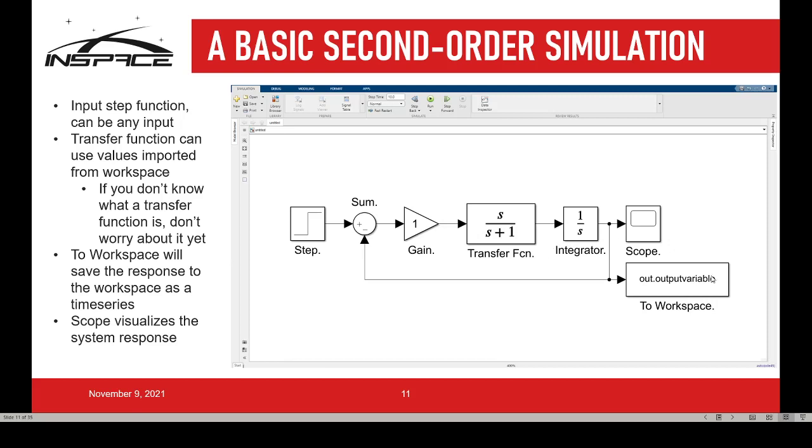These are pretty common outputs that you see when you're working with pretty basic Simulink. The first one is scope, which I actually have them both on the next page. But doing an output to workspace, basically, like I said earlier, throws it in MATLAB, where you can work with it. It's going to be a weird variable type called a time series, so you need to do one additional step to convert that to either a matrix or an array or whatever you want to do with it. But then it's in MATLAB for you to use, and you get to assign the variable.